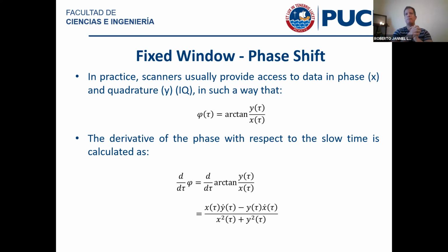So if you had, for example, a signal that would be 1 kilohertz in bandwidth, but it has a carrier frequency of 100 megahertz, just to give a ridiculous example, you could either digitize it at 200 megahertz, or you could bring it to baseband. And because it only has a 1 kilohertz bandwidth, centered at 0, so you have half a kilohertz on both ends, you can digitize it at 1 kilohertz and get it over with.